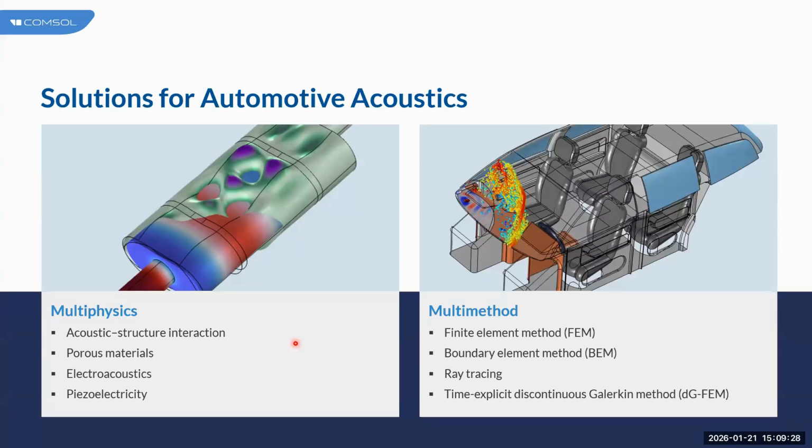So here, what you see in this slide are the solutions that COMSOL Multiphysics has to address automotive acoustic applications. Most of the applications are multiphysics in nature, and many of the problems require vibroacoustics in modeling the acoustic-structure interaction, where you model the elastic waves in solid and the pressure waves in fluid, and you need to couple the interaction between the two. So the noise here can be a structure-borne noise, or it can be a vibration-induced noise as well.